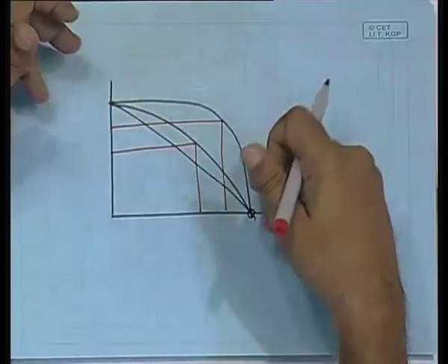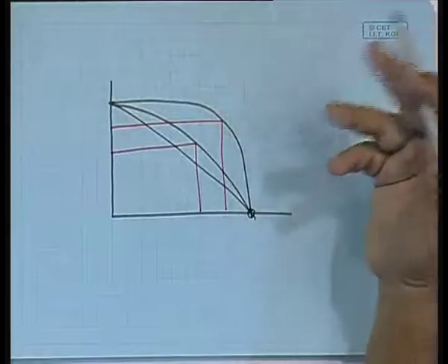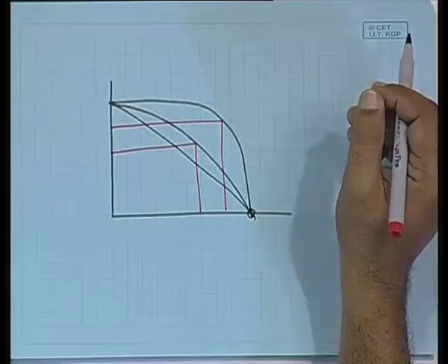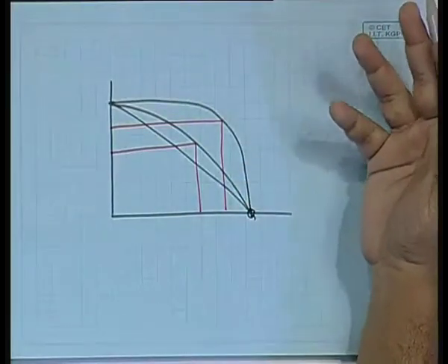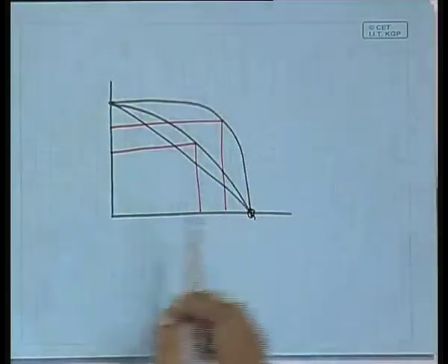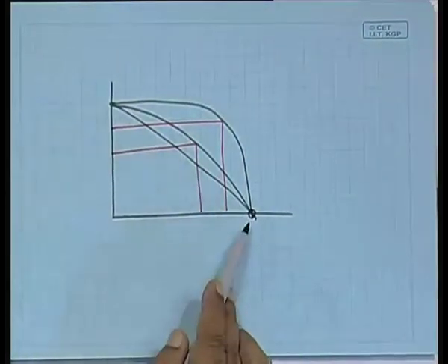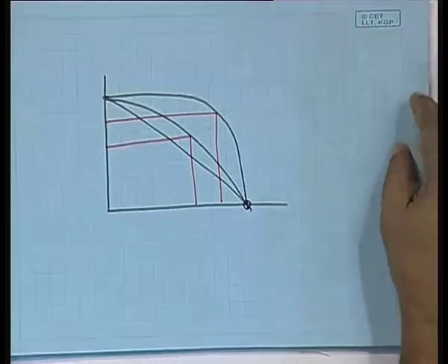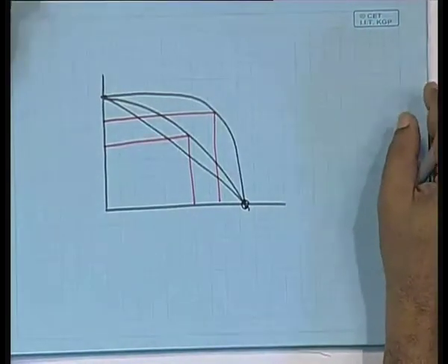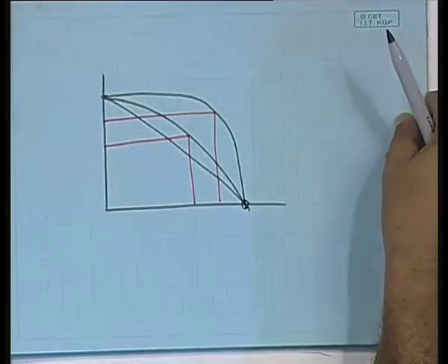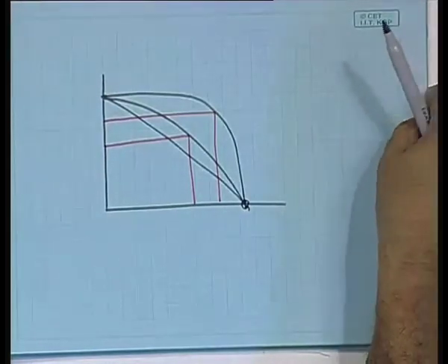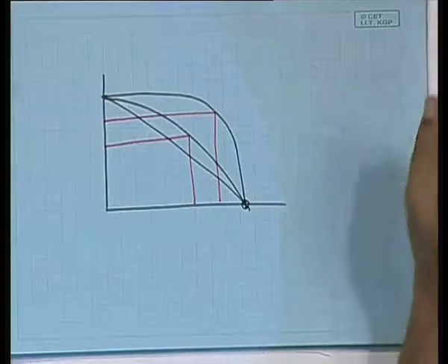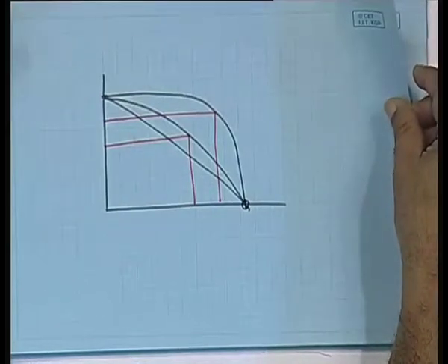Actually, these characteristics depend on the value of the series resistance and the shunt resistance. As the series resistance increases and the shunt resistance falls, the characteristic goes from this kind to this kind. And that is why whenever an energy engineer or anybody exposed to energy engineering wants to buy a photovoltaic panel, he should immediately ask for the fill factor, not only the open circuit voltage. Is that clear? Fine.